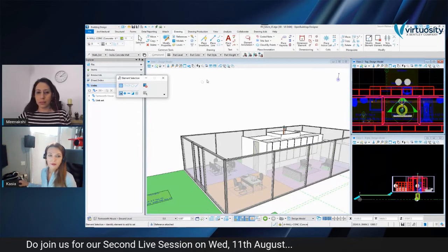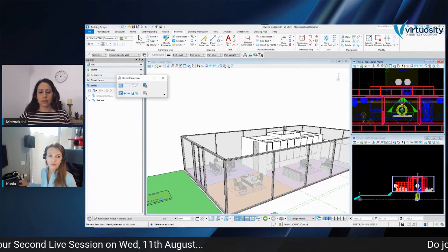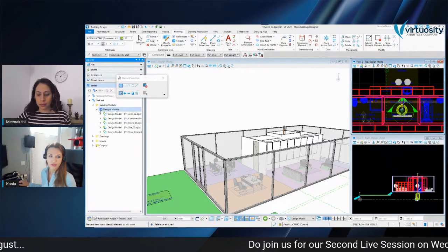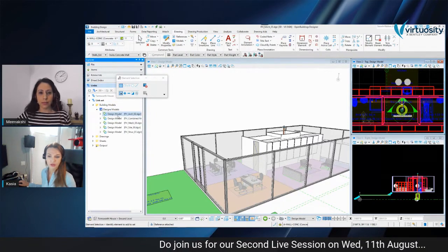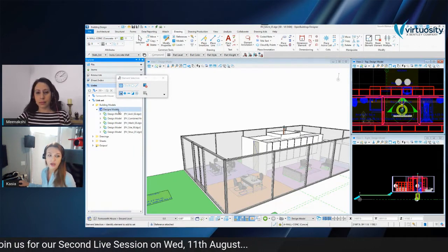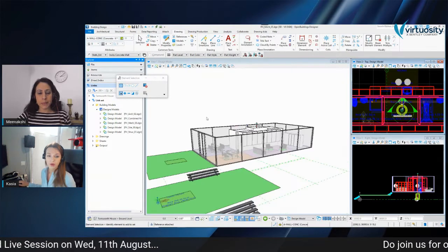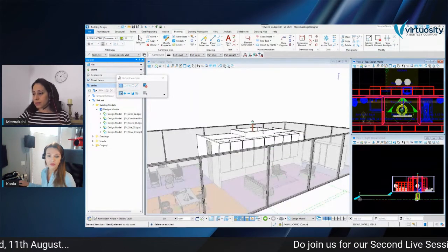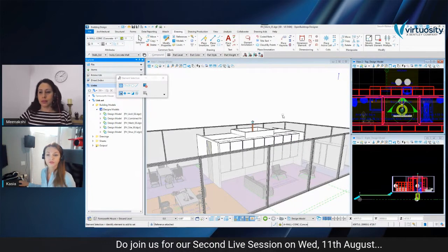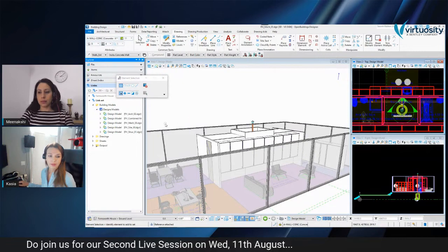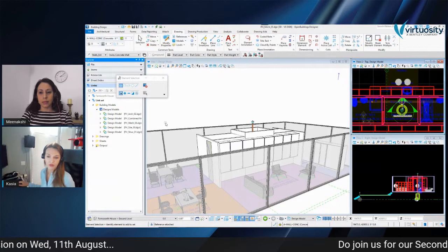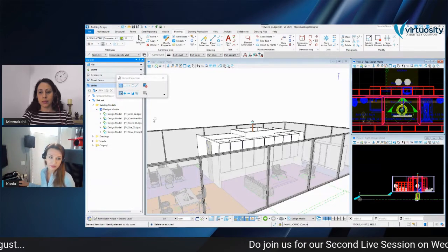And another useful case when we can use the federated approach is, for example, in skyscrapers or other bigger projects where we have repetitive typical floors. For example, we only need to prepare one typical floor, and then we can attach it many times in a master file. And then if we need to change something there, we can simply modify one file, and then all the references get updated.